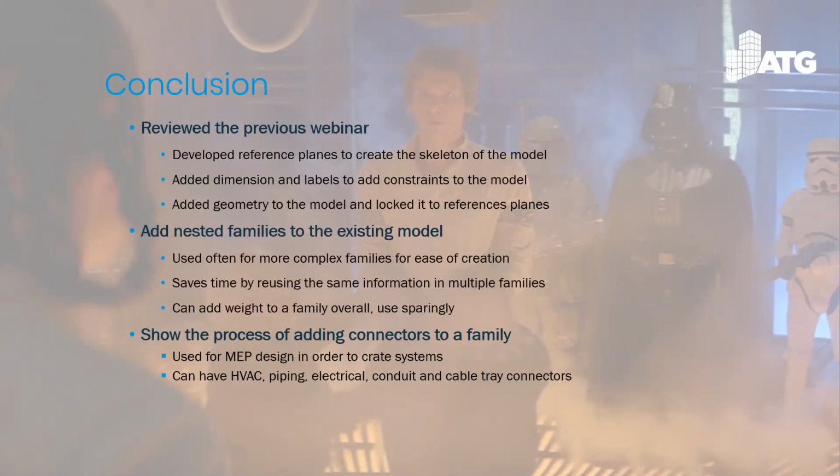If you're getting into that much detail, you want to go into Inventor or SolidWorks to create your assembly models. But with Revit, we want to keep those family sizes down. Try to get them to about a meg or less. That's always my goal as I create families within Revit.